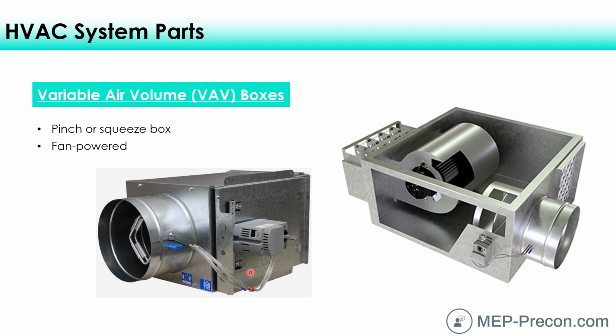that room. So the thermostat senses that temperature and it says, hey, do something, system. And it doesn't necessarily know what it's connected to, but this actuator receives that signal and says, I know what to do. I'm going to open up this damper to provide more cold air into the space to offset the fact that there's more BTUs in that space that's creating a hot environment. And so it does that, and it finds its equilibrium and keeps the temperature cool within that space.